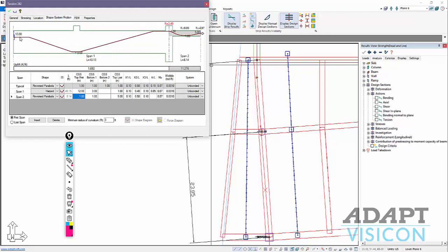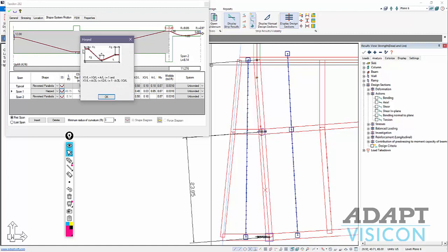We can change this straight extension here. I'll also say that's 0.03. And then we have the same thing on the opposite side right there. Let's see, that's 0.03. Oops, that's the mu coefficient. Let me change that to 0.03 here. Okay, so make sure those are correct. These variables are defined if we go to this little image. X1 is from left end, X3 is from right end, A, X2 is to the center of A for the harped shape.